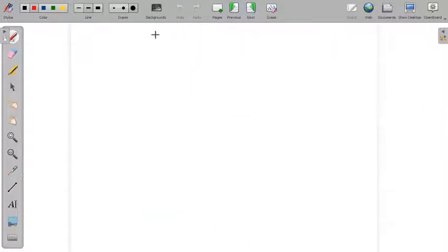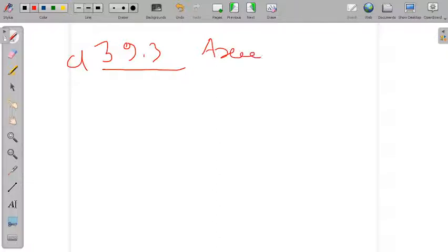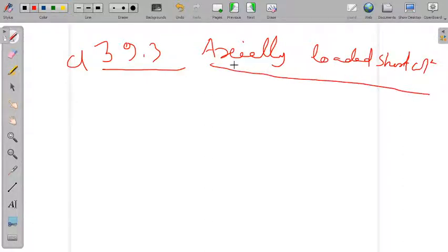We'll go to the next page and see what is written. Basically we have to see clause number 39.3. Clause 39.3 discusses axially loaded short columns. So how do we know a short column? If the slenderness ratio is less than 12. So, axially loaded short column. What is said? The member shall be designed by considering the assumptions given in the clause and the minimum eccentricity.